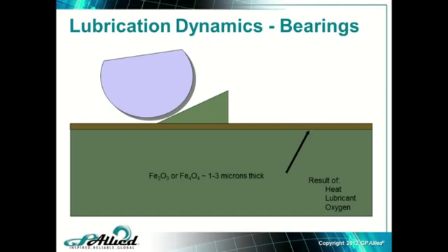Right? So the best example of this would be we were measuring vibration at a plant, and we'd been there a long, long time. And this one particular pump never had any problems. But over the course of the years, we could see the vibration data showing that the bearing's just getting progressively more and more loose, which is exactly what happens here. We're eating away at the inner and outer race, so you can imagine the internal radial clearances of the bearing are getting bigger and bigger as each moment passes. Right? Now, how long should that take? Well, we monitored it for the better part of 12 years, and there was no record of it ever having been worked on.